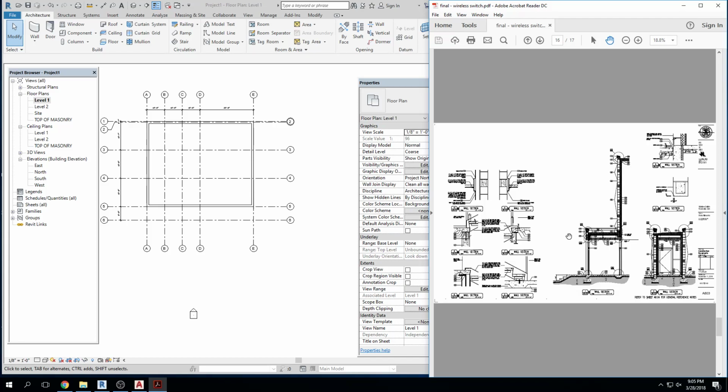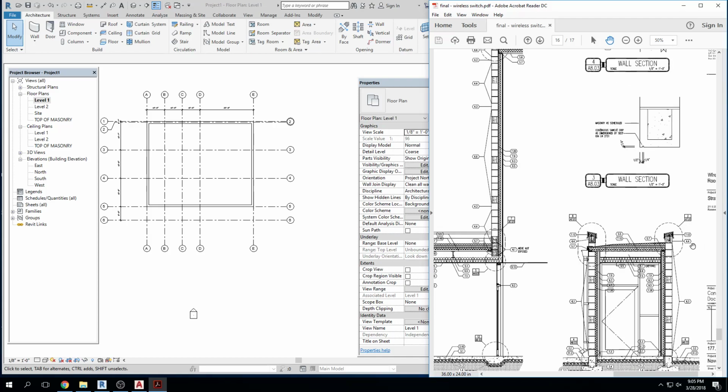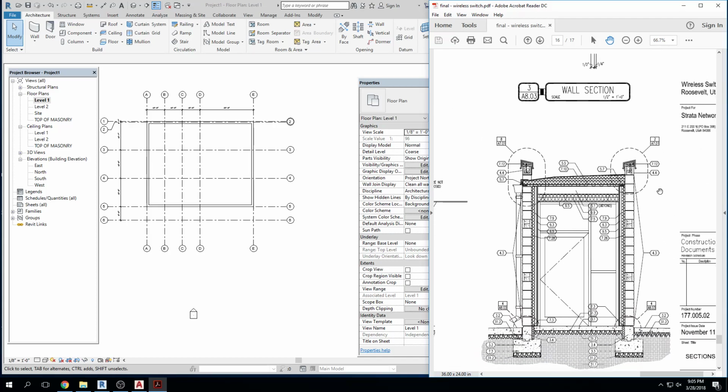What have I done wrong with my grid when I'm not seeing the A at both ends and the B at both ends? If you click on the grid, go down to where you're not seeing the annotation, there's a little check mark you can check and it turns on.